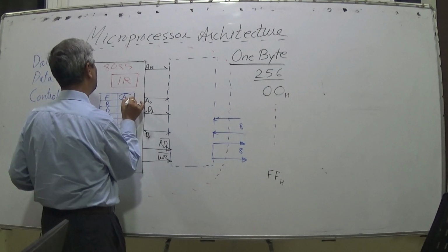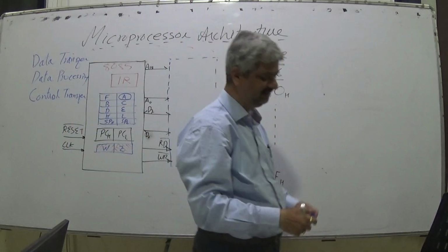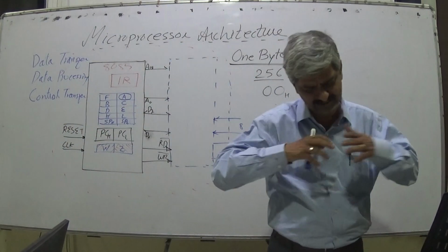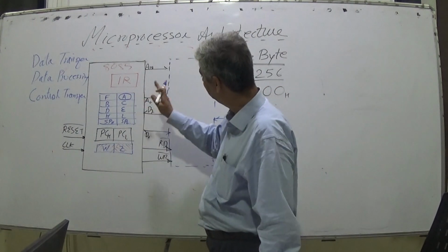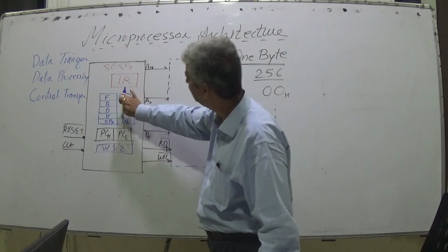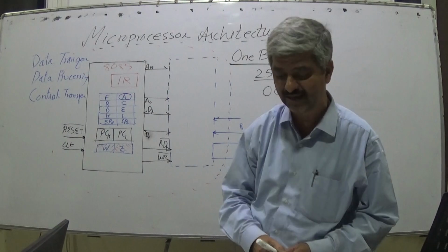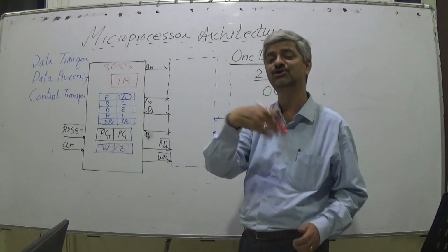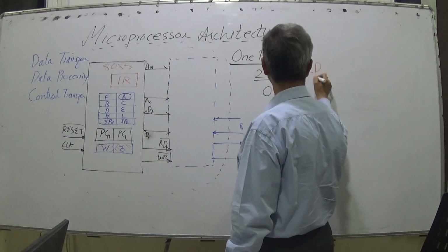Many operations are possible only with the accumulator. That is the design limitation of that time. Now you will find more generic microprocessors. So something from a location outside to here, or from here to outside: those instructions are called load and store. Load, which we saw last time, and store.